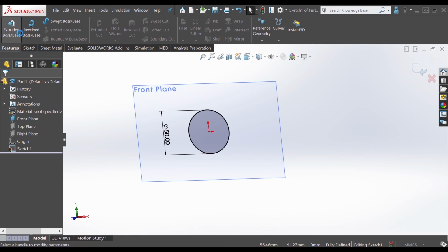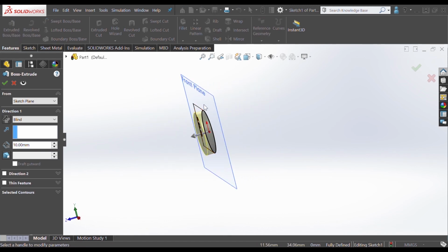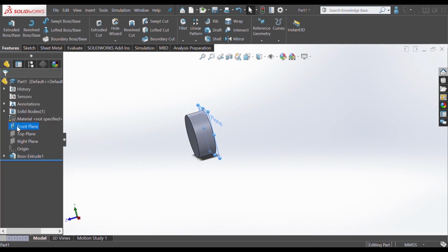When you press extrude, you're going to see a yellow shadow appear from the circle, the original sketch, and it extrudes the base to a certain length or height, and you can change this length depending on this number. Here it's extruded 10 millimeters. You can go for, I don't know, 20, and then press enter, and you're going to see a preview of that. If you're happy with 20, you just press OK, and there it is. You can just hide the display. There's your 3D shape part, and that's pretty much how you design a part.